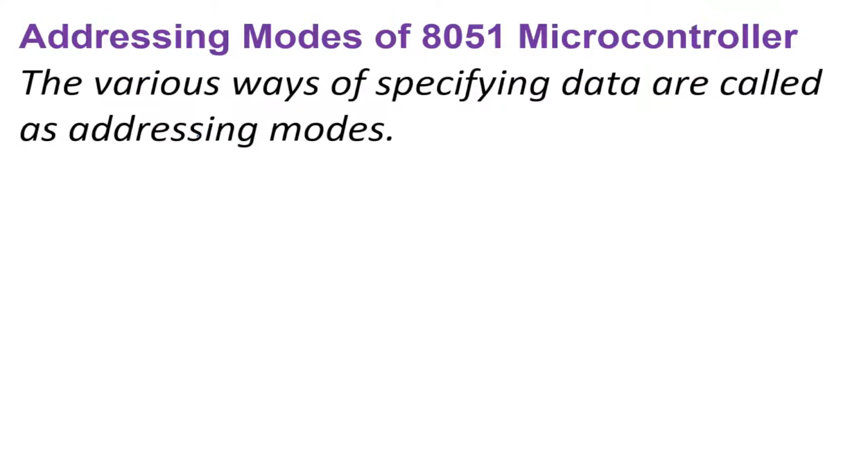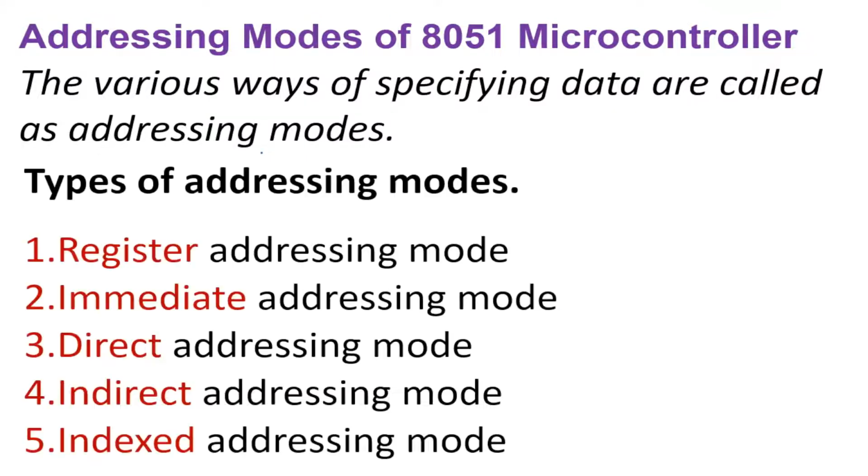Welcome to the session on addressing modes of 8051 microcontroller. The various ways of specifying data are called addressing modes. It means that when you specify data in the instruction, in what way it is specified, that decides the addressing mode of that instruction.